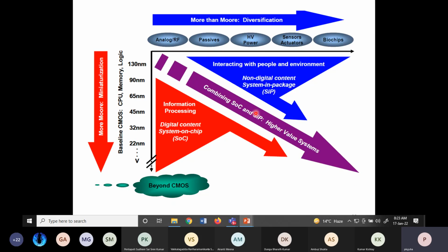Okay, on the same system, or making the same system. SiP is system in package. So in a package you can integrate different systems, maybe sensors, maybe power devices, maybe your CMOS, and so forth. That's basically system in package, and SoC is system on chip. On a single chip you can make several systems like a processor and so on, or maybe very application specific integrated circuits like your ASIC chip, right? So that is system on chip, and here we are talking about system in package.